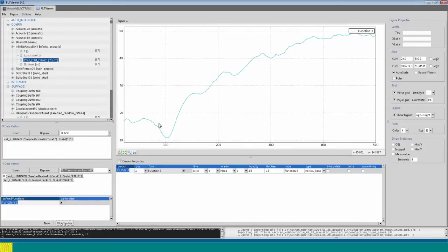So typically at lower frequencies, in the very low frequencies, the system is controlled by the rigidity of the structure, and then we will have the first modes of the structure that will dip in this frequency. And then typically, if the problem has little damping, then we will have quite shaky curves, which is the zone controlled by the structure modes. But as we have some damping in the system, we don't see too much of that phenomenon. And then at some moment, as the modal density increases, we will enter a mass law region where the curve goes up with a constant slope.